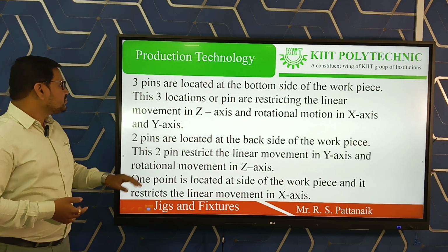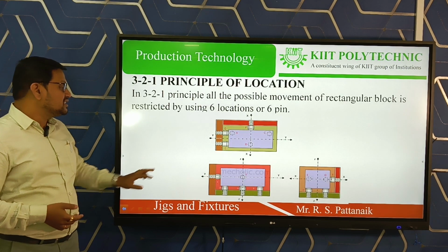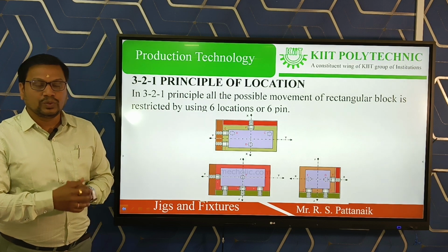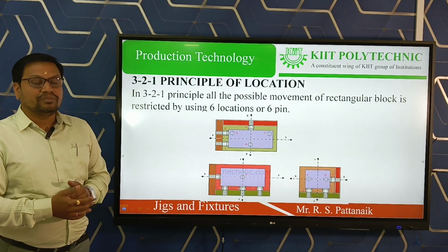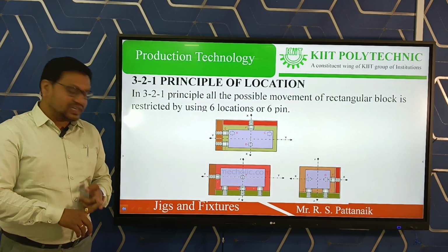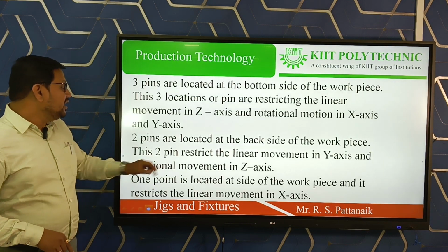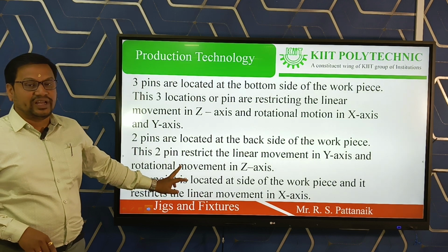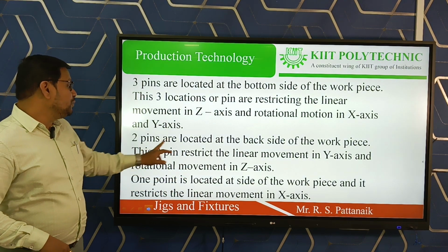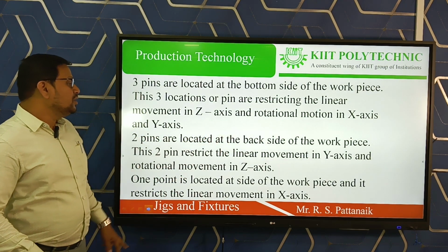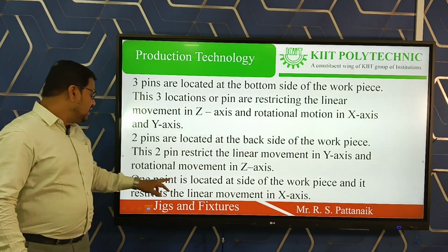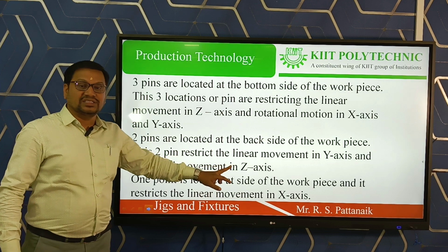Next, 2 pins are located at the back side of the workpiece, which restrict the linear motion in the y-axis and the rotational motion about the z-axis.